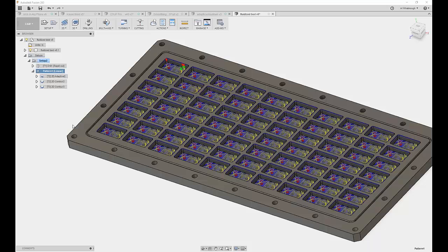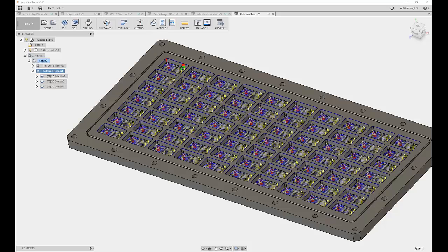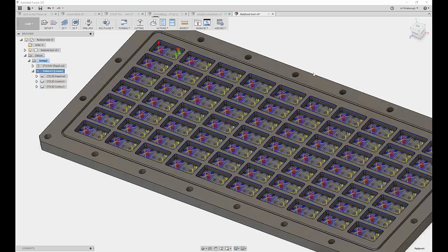One quick note, Ben, on the post processor for the RoboDrill, right now it's only in that FANUC post processor. Bob is looking for people to test the logic and work through it. It currently only works in the XY plane too, so you're probably thinking you're wanting to do it on your little tombstone. That's not going to work right now, but if you're looking at testing the logic, there's a forum thread to search for to go take a look.